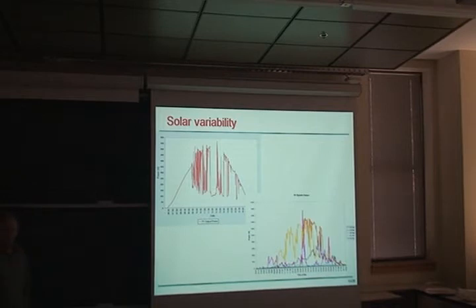So there's pressure on the standards bodies to reconsider that and think through the right way of introducing voltage regulation capability at the inverter level. Then every individual house with a solar panel would be contributing to keeping the voltage constant. It makes sense conceptually, but it's quite challenging to do technically.